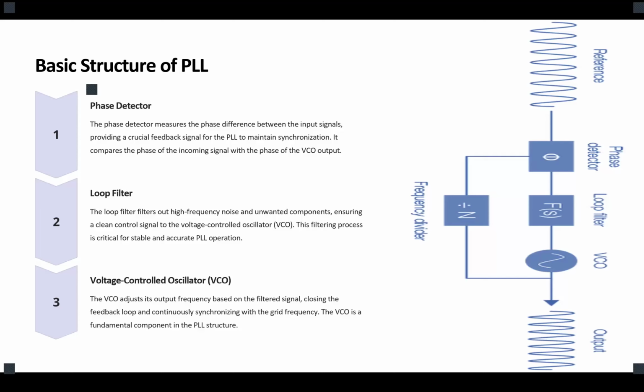If you're feeding it the sine, are you saying we change the sine that we're generating to a different one? It is not a constant. That's what I'm saying. When you add the PLL, the frequency of the VCO is decided based on the real-time measurement. You're thinking it's constant? No, it's not.